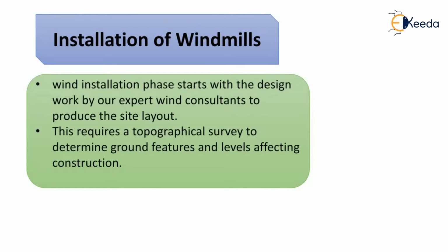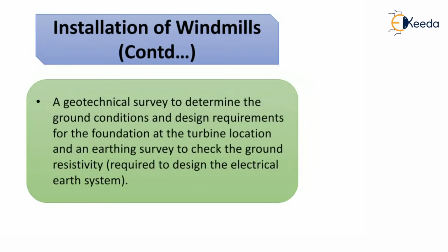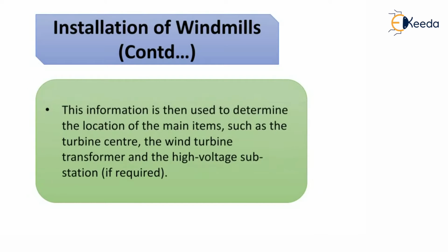Installation of the windmills. The installation starts with the design work by our expert wind consultant to produce the site layout. This requires a topographical survey to determine the ground features and levels that will affect the construction process. Also, a geotechnical survey is done to determine the ground condition, to design the foundation, and to check whether the ground resistivity is proper for earthing.